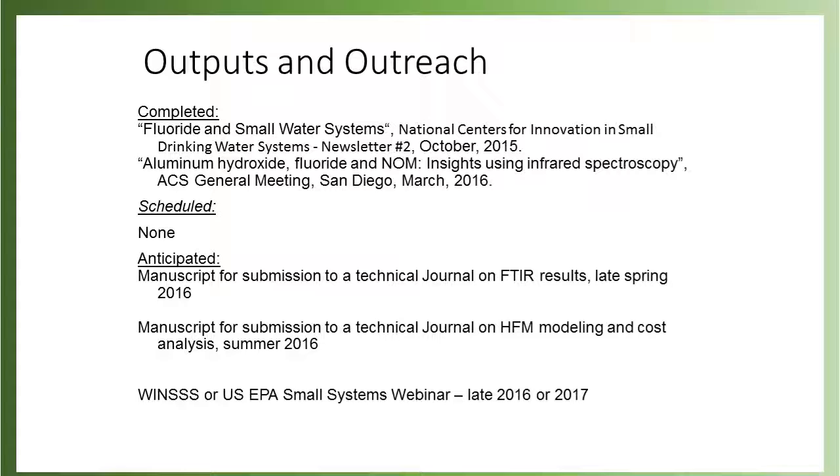So I have a question for you all. If you run an iron coagulation system, what pH do you want to be at? Well, mid-5s is our pick for our study that we've done, for iron coagulation. But what do you see? If you're a small system, you want to coagulate at whatever pH the water is coming in the door at, adding whatever amount of alum you're going to use. You don't want to fool with acid, is my point. Yes. But what do you typically see with iron?